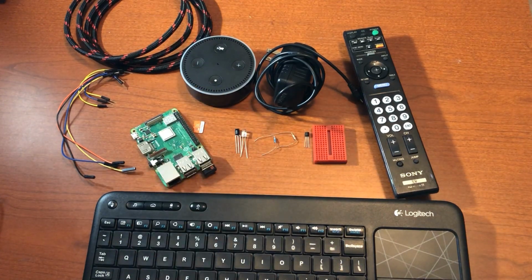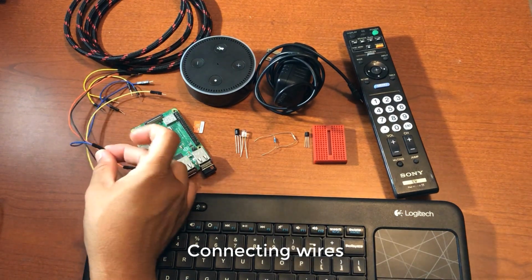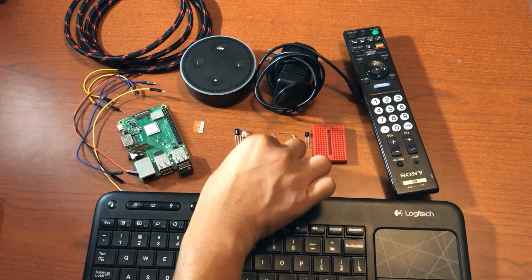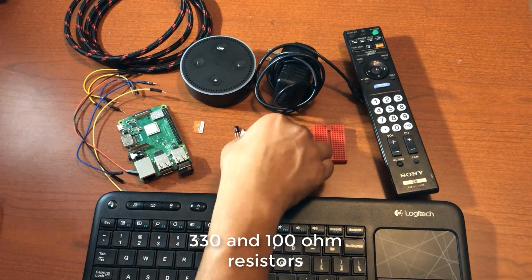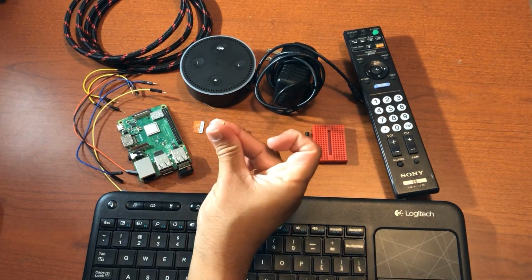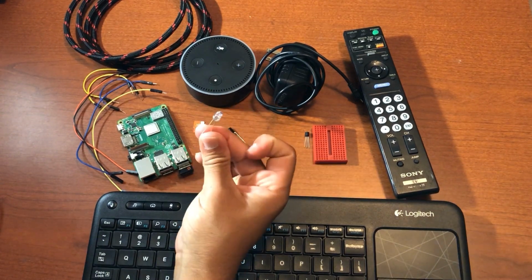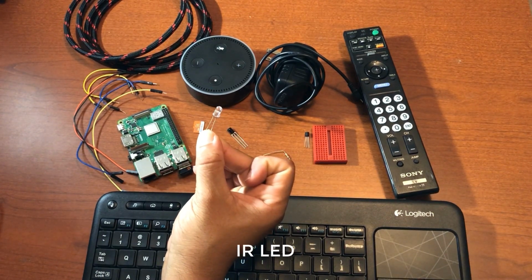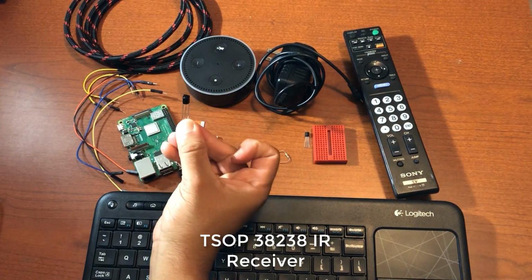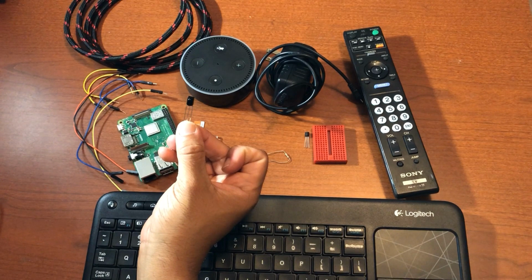Next up, for our IR circuit components, you'll need some connecting wires, and male to female connecting wires are handy. We also need a couple of resistors. Here is a 330 ohm resistor, and I also have a 100 ohm resistor. Next, we need an IR LED, which is the infrared LED that we'll use to send signals to our TV. We'll also need an IR receiver, which is what we'll use to record signals from our remote.